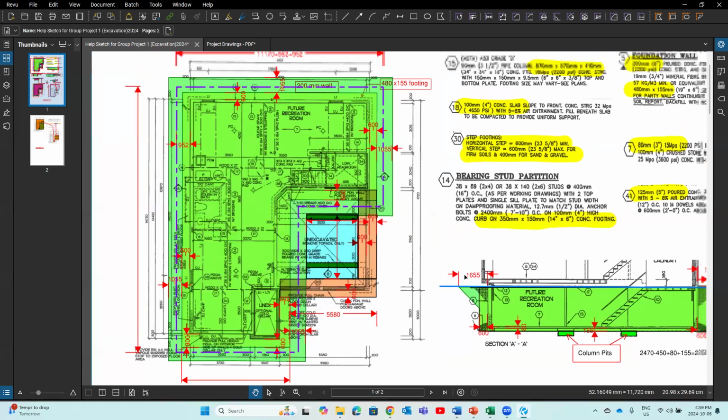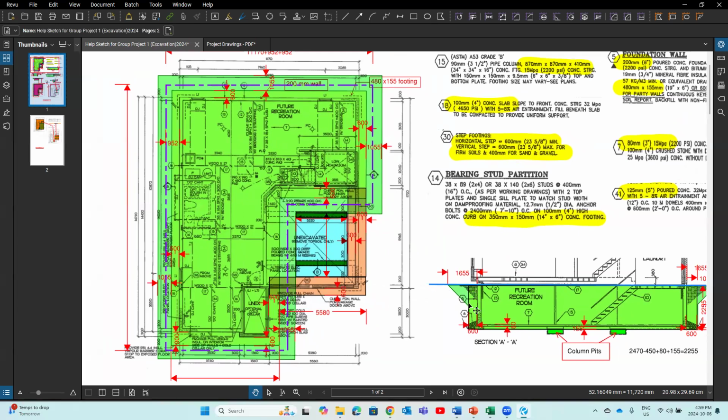And if we want to draw this slope, this triangle part, that's this color all the way around. Make sure you imagine this in 3D. That's all the way around. It's not only two triangles. That's what you need to visualize in your mind. It's a slope all the way around here. Okay, if we can draw this under the foundation plan, now we can start to measure the quantities for basement excavation.